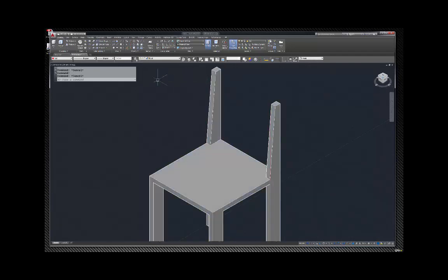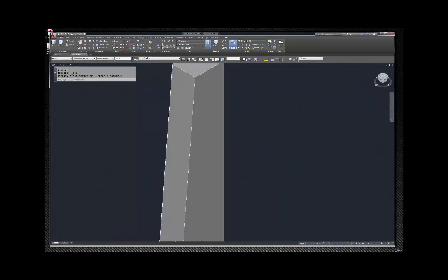Then here's one of the things you can do with go to box. Now pick this plane here and notice it aligned. Okay, watch carefully now. I'm going to zoom in here. When I pick box, notice how my blue cursor is straight up and down. As I come over to this face, notice that the blue cursor changes. So I am now drawing on that face.